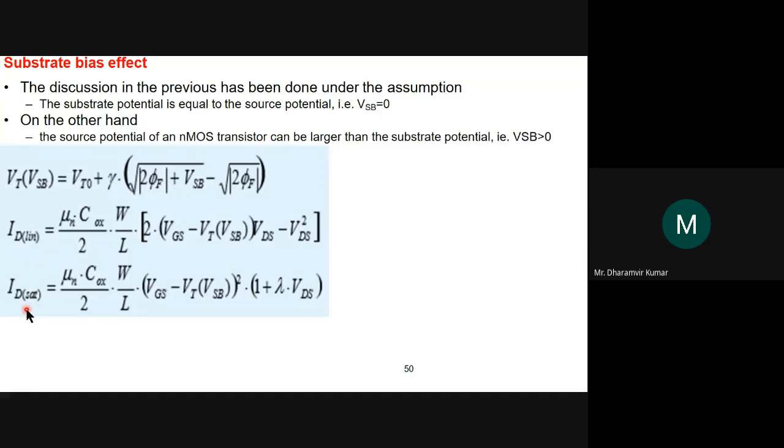Now look at here, the saturation current is given by this equation. Okay, this parameter is same into VGS minus VT whole square into 1 plus lambda VDS. Now this 1 plus lambda VDS is coming from that channel length modulation effect. And again this is VGS minus VT whole square here. So again if VT becomes a higher value in the case of NMOS, this term will become lesser, this whole value will decrease, and we would expect that the current starts to